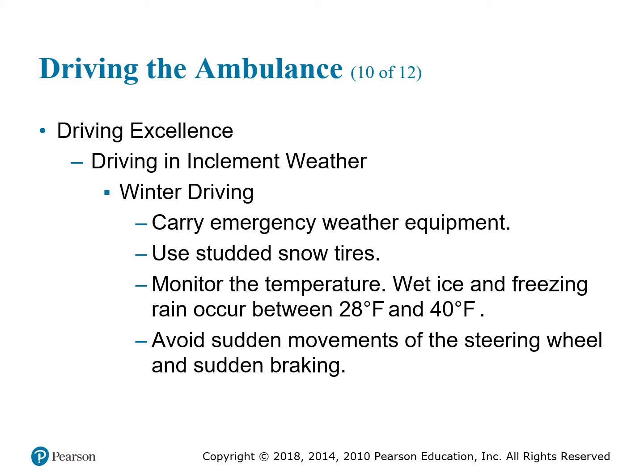Winter driving: carry emergency weather equipment, use snow wheels, monitor the temperatures. Wet ice and freezing rain occur between 28 degrees and 40 degrees. Avoid sudden movements of the steering wheel and sudden braking.